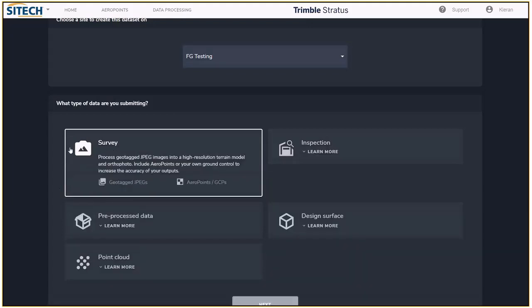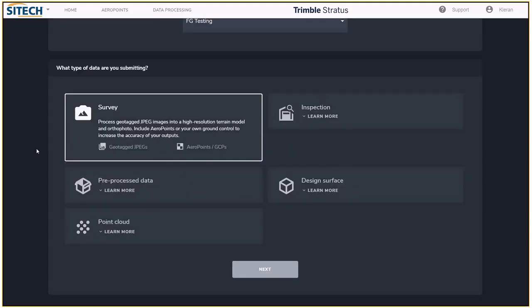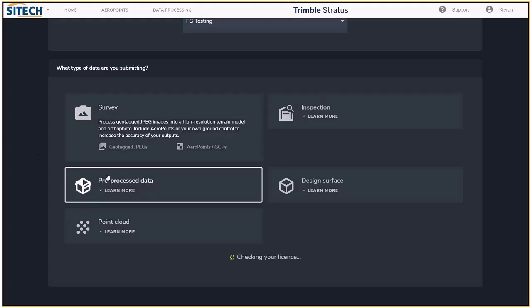And it'll give us a little spiel. The traditional one is the drone survey. So where we use our drone flight planning software, we capture our grid of photos. We've got a GCP file from somewhere. We upload those, away we go. We can set filters on that, determine what we're going to use as check marks or ground control. This can take RTK, PPK data with fewer ground control points. Basically an upload process, and we'll get an email within about 24 hours to say, hey, that's all ready, which is great.